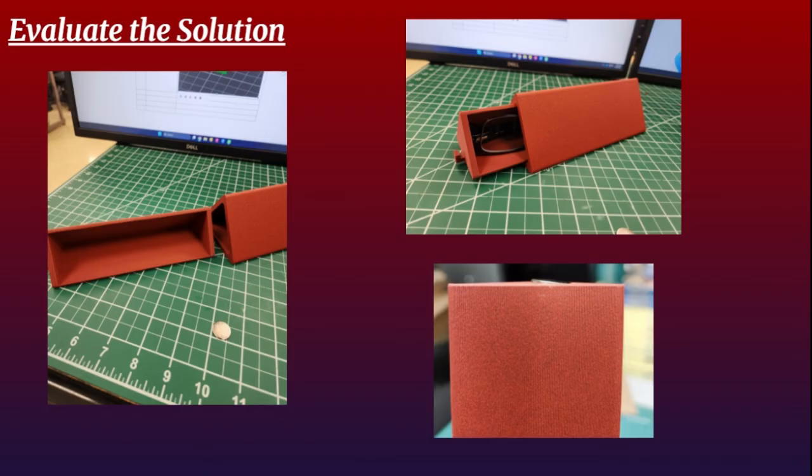After removing the tree supports, I tried inserting the magnet inside the hole on the back, but it couldn't go in. The hole I made for the magnet was already super tight due to my small tolerance, but the tree support residue present in the hole made it impossible for the magnet to fully go in. The picture on the bottom right shows you how the magnet sticks out. No matter how hard I tried with pliers, I couldn't get the residue out. But aside from the magnet issue, the case worked perfectly as intended. And since the shell functioned as it was supposed to, that meant I could reuse it, and the only piece that needed to be readjusted was the case piece.